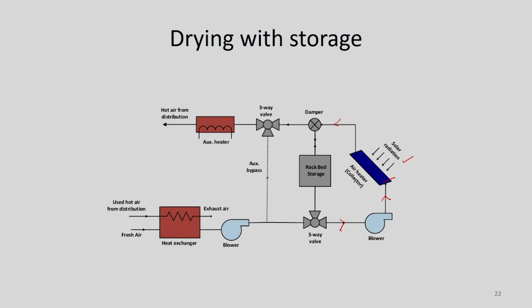If we have generated more than the required air, then we can store it using a rock bed storage or some other devices. Whenever required, that can be used for process heat applications. Sometimes we can use the exhaust of an engine to harvest waste heat for drying of other agricultural products. At the same time, we can connect that system with the solar air heating arrangement, so that when solar is not available, this facility can still be employed for generating hot air.